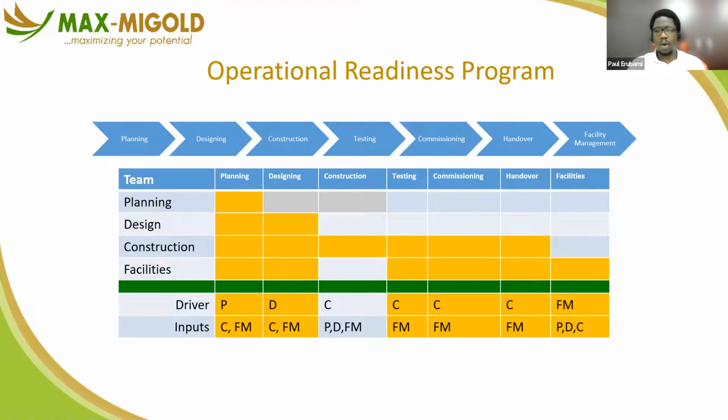Now, with that comes the documentation of what is being done, including documentation of the changes, so that whenever a change that goes through the right process is implemented, it is also documented that this is what it is now. So the as-built bill of quantities and as-built drawings we talked about are beginning to be developed because you are documenting changes. Then in the construction phase, you have the quality assurance and quality control processes. These two processes are combined in what comes out as the output of our testing and commissioning we'll be talking about in the next phase.